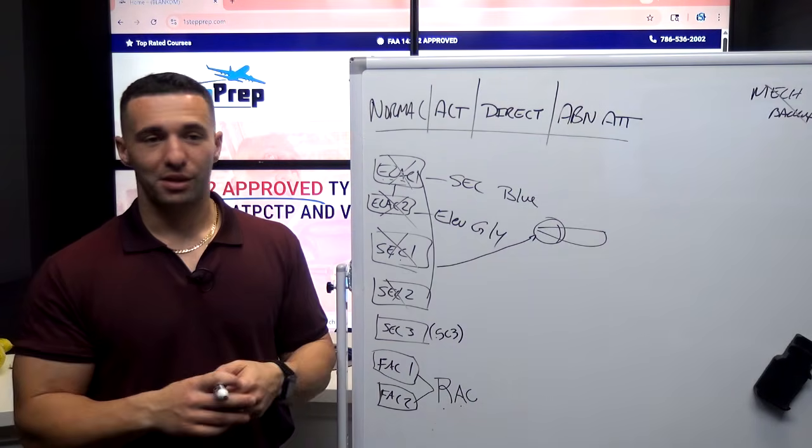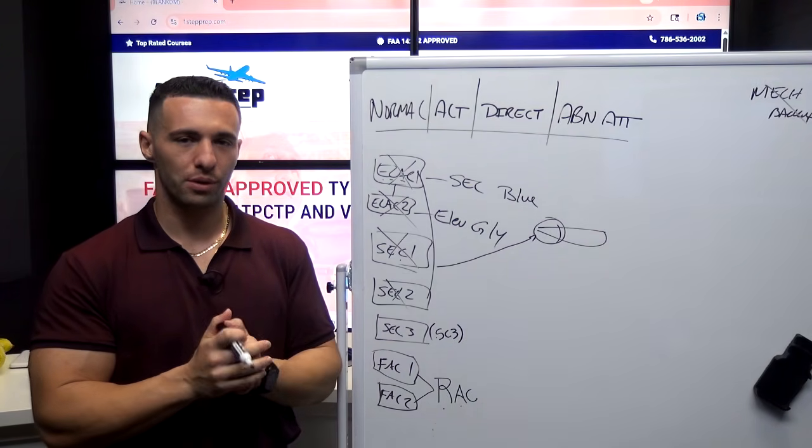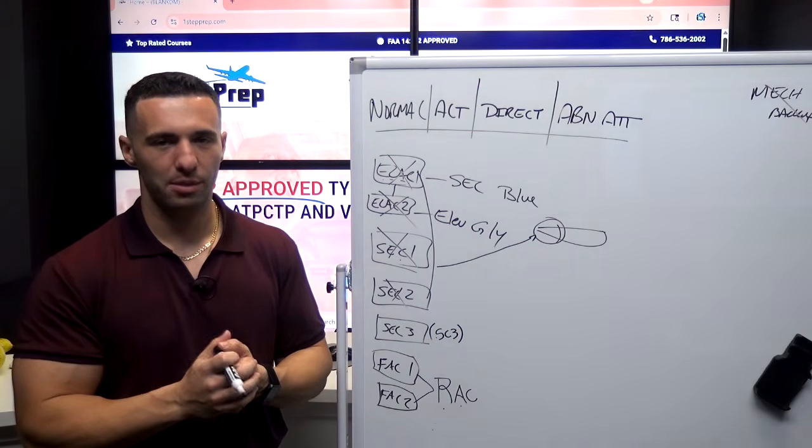And I have thrust vectoring. So I have rudder, I have pitch trim, and I have thrust vectoring left-right to control the roll axes. That's how we get around in mechanical backup.